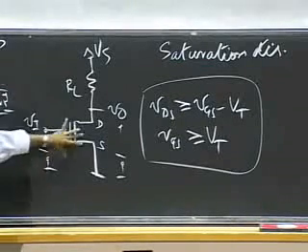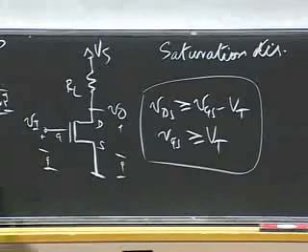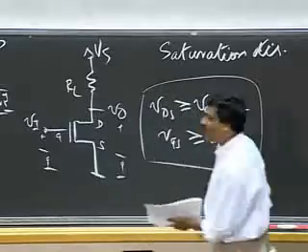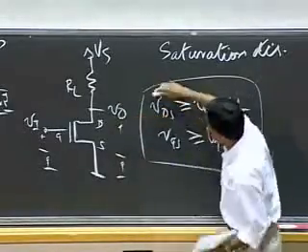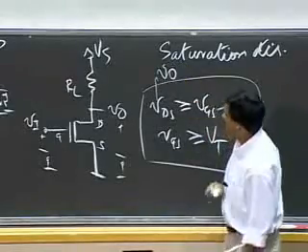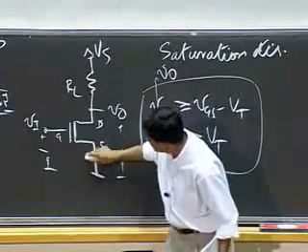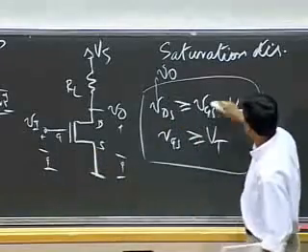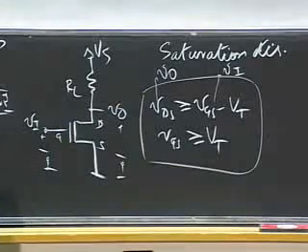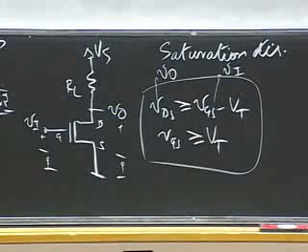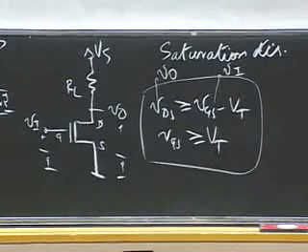Okay, what that means is that you can begin to model them as a current source and simply analyze the behavior accordingly. One minor note: VDS for the MOSFET is the same as V0. Okay, and VGS for the MOSFET is the same as VI. So if you see me blithely jumping back and forth using VOs and VIs, or VDSs and VGSs, they're the same thing in this circuit.